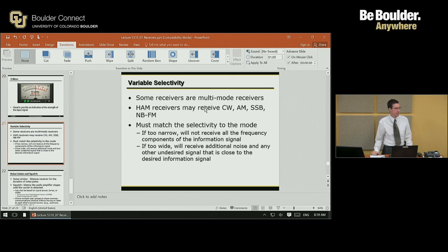It has a single sideband. It's called continuous tone because the way you generate Morse code is that you have an oscillator that transmits at one particular frequency, and if you just hold down the Morse code keyer, there'll be a continuous tone. But as you know, when you do Morse code, you're going da da da da da da da da. But it's continuous because if you were to hold that key down, it would be continuous at that one single tone.